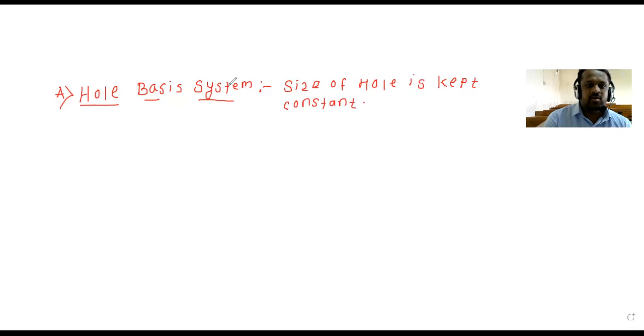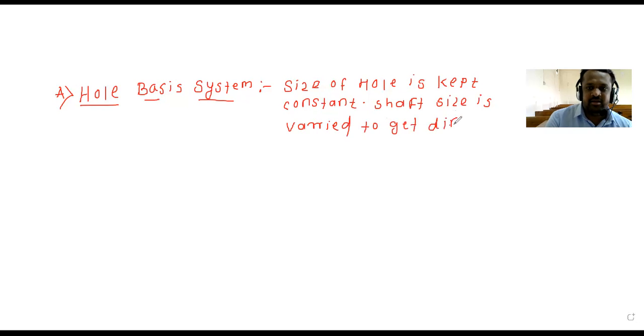In the hole basis system, you have to remember the size of the hole should be kept constant, and the shaft size is varied to achieve the different fits.